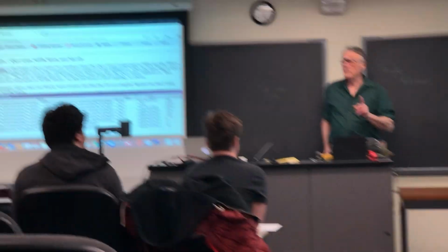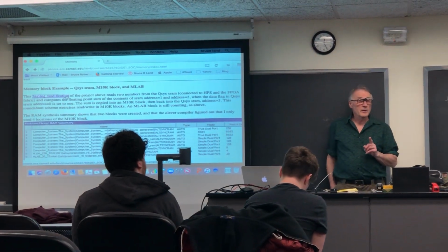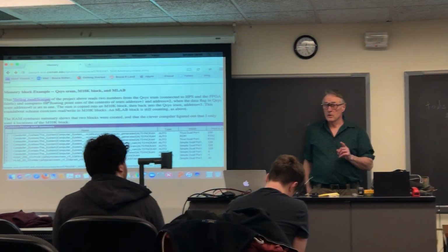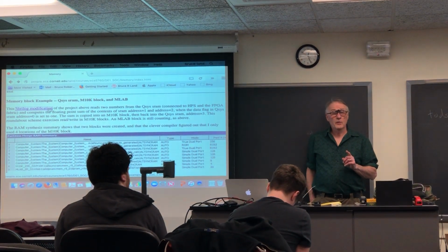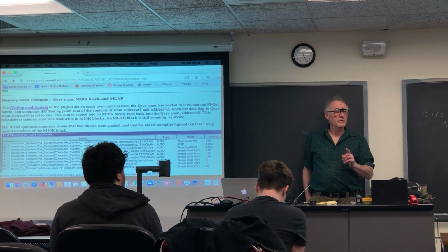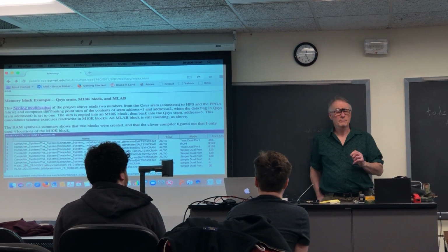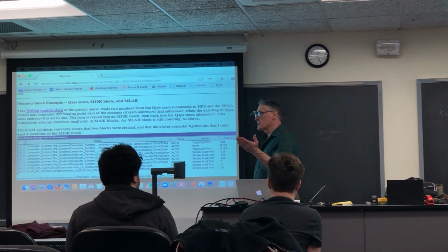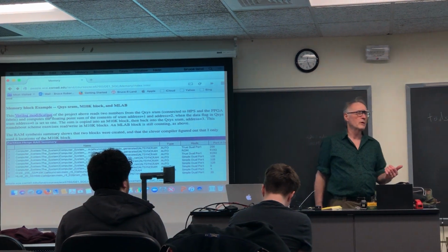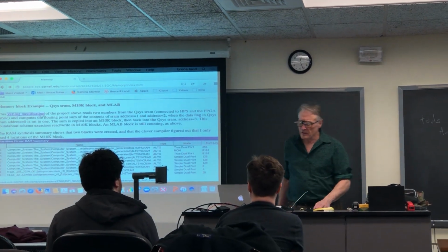For both M10K and MLab, there is no automatic global clear. If you code a global clear into your module, then the compiler will say those blocks don't support global clear. It will assume you want logic elements as memory, and turn it back into logic elements. If you do multiple accesses on a single clock cycle, the compiler will also convert it back to logic elements. So, you know, it takes some care.